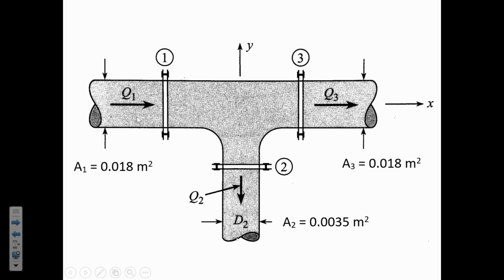So I don't want to spoil all the thought that you've got to do to solve this one. But what I'll say is that it doesn't matter what direction the flow is. So here at 3, even though the flow is to the right, the pressure is still pushing to the left. And so there's going to be some effect of the pressure at 3 times the area at 3 because we cut this pipe. But that external force is acting to the left, whereas here it's acting to the right. So that's important because of what it means to the left-hand side of that equation.